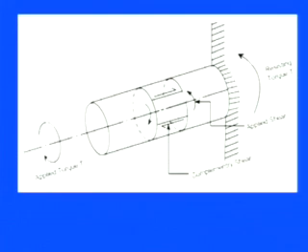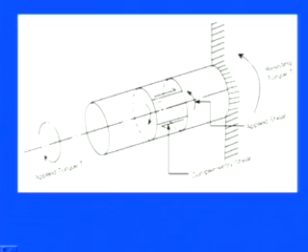Rather than on the axis part. So the shear stresses being generated are not along the axis; they are always along the circumference, or we can say along the plane. Due to the rotation, we have a shear stress applying in this direction. This is the shear stress induced because of this torque.